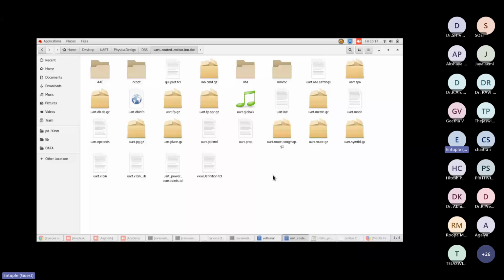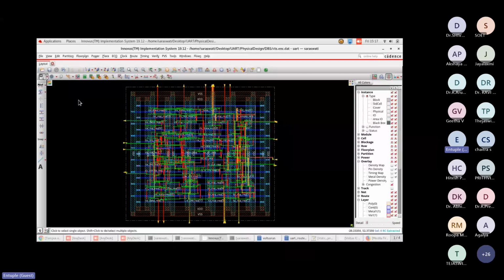So CPF, common power format, UPF, common power format, all those things have their own separate flow for low power to realize your design. So this is how a basic check, a basic power analysis using Voltus works. If you go in detail, you can find the rail, IO rail. This is the block level only. If you go for chip level, you have the IO pad related power analysis, and IO rail connections, connections like IO pad related rail connections, and also mesh network.